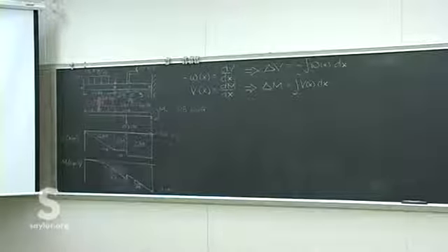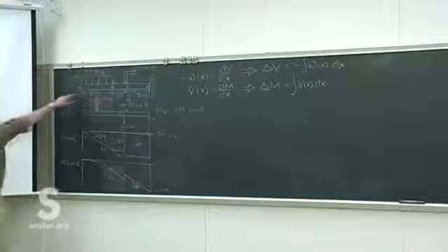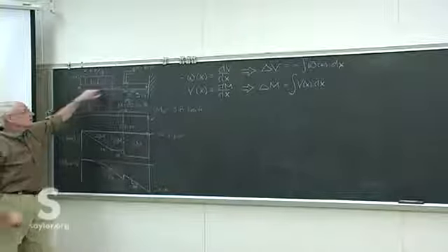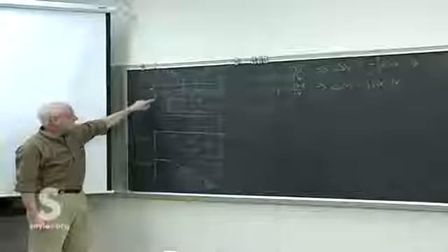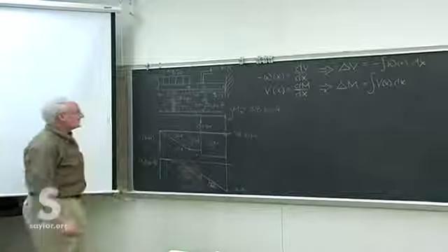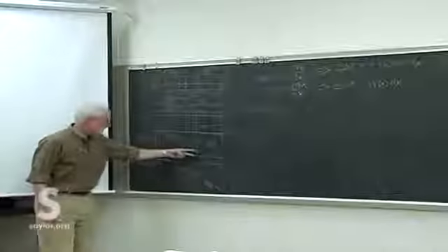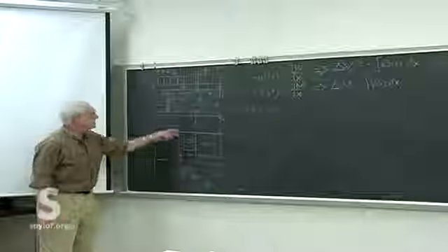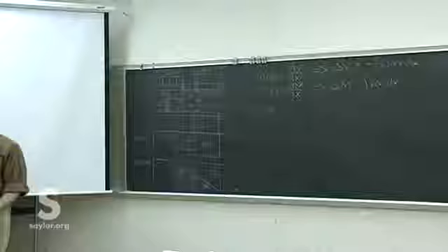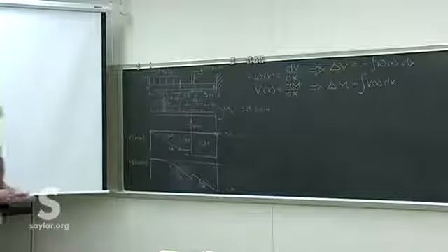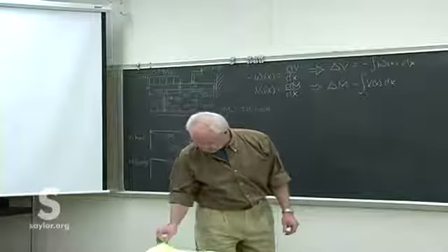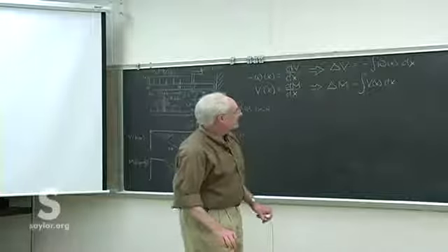So we have those four relationships, plus any of the point values that we happen to understand, especially at the free ends or at the reactions. Combine all that with the known jumps because of either applied loads, moments, whichever might work, and we can complete these.